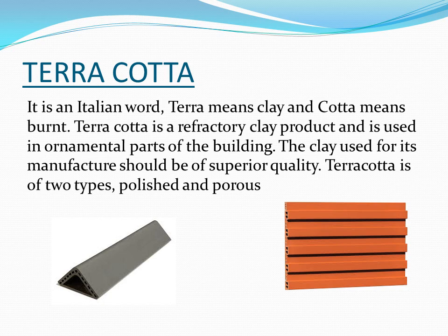The clay is mixed with powdered glass, pottery, and sand, ground to fine powder and pugged several times till it gets uniform and soft for molding. Terracotta is impervious, hard, and cheap. Where properly made, the material weathers well and because of its glazed surface can be cleaned easily. The product is burned in a special kiln, that is a muffle furnace.